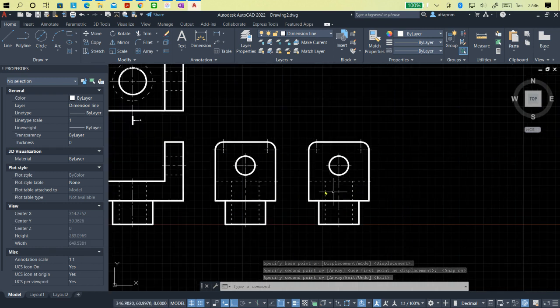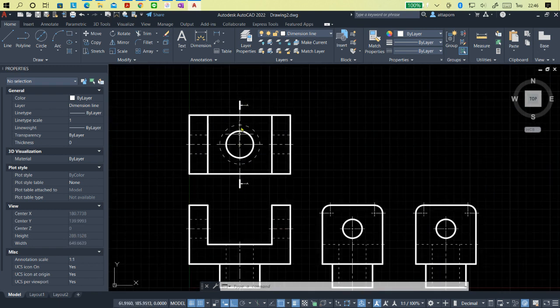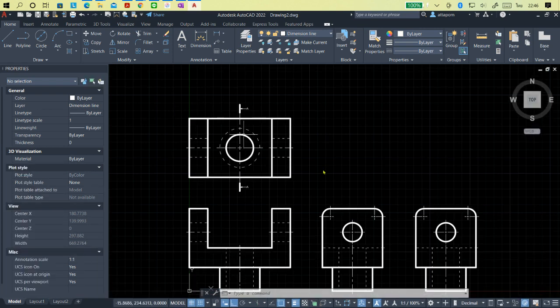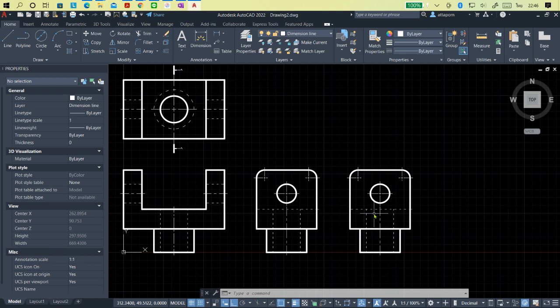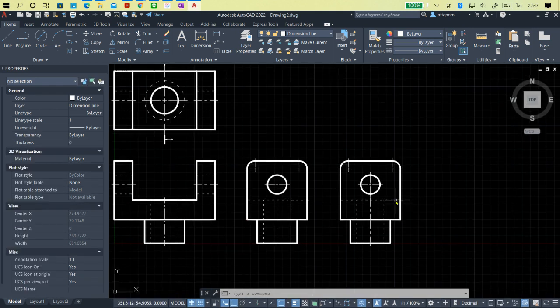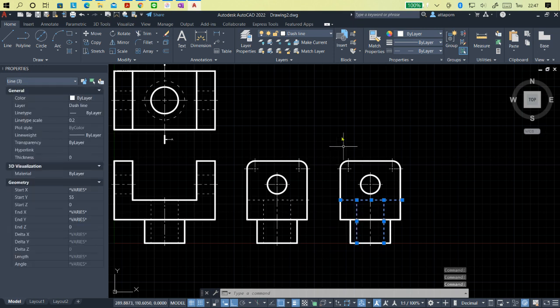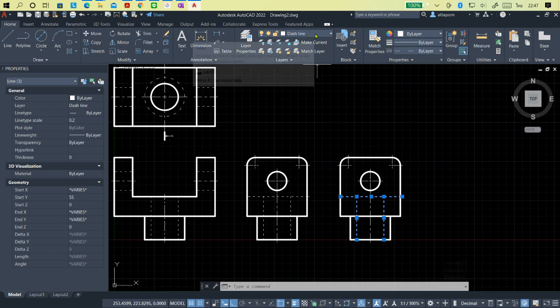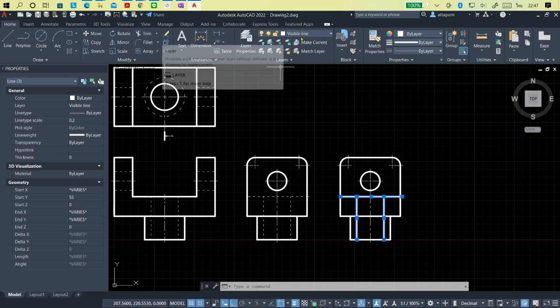Okay, so we will modify this one to be the sectional view. Let you imagine that after you cut this and see in this way, you will see something change from dashed line to be a visible line. So let me change the dashed line first to be visible line, which will be this and this. You choose three of them. So now there's dashed line. So you change it to be visible line by changing this property.